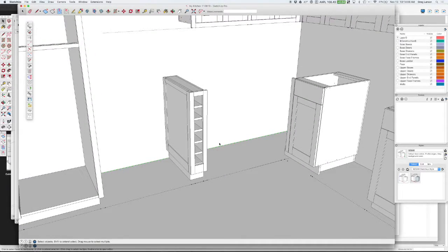But if you recall, when I draw this in with some other cabinets, when I'm using the divided base cabinet, I can only have divided bases connected to it to make a multi-bay cabinet. But what if I want to just put a standard cabinet next to this? Well, what I can do is grab my story stick tool and go down here and draw the left style of this cabinet overlapping the right style of this cabinet.